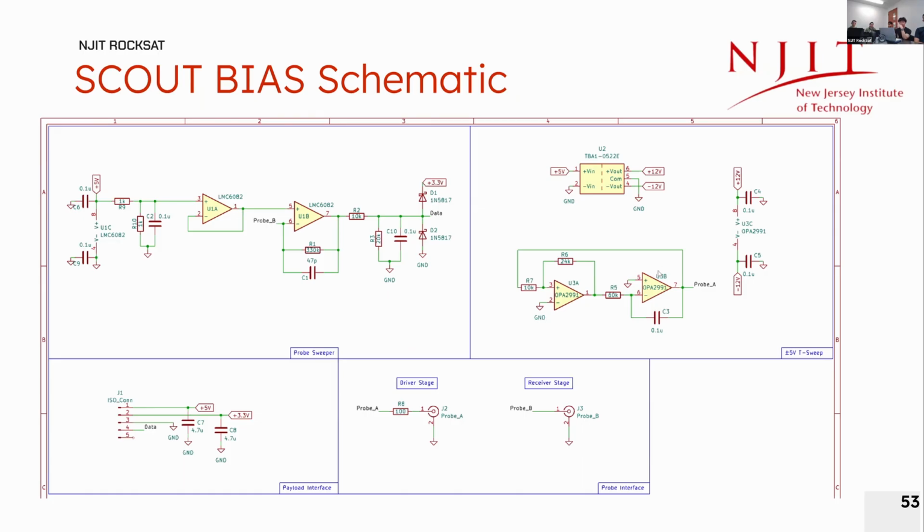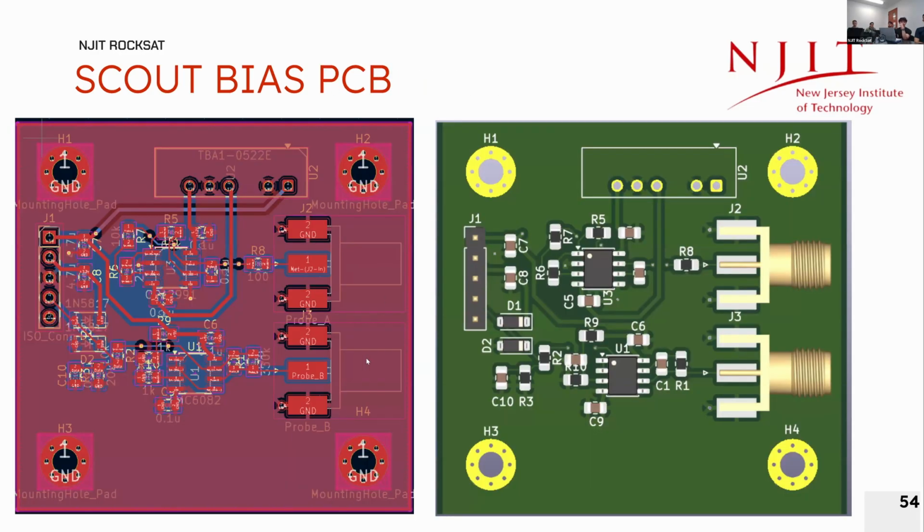This is the triangle wave generator to bias the first Langmuir probe, and the second Langmuir probe will input the current into the transimpedance amplifier and give a safe reading for the Arduino. And of course, it connects through a connector for both cores as well.